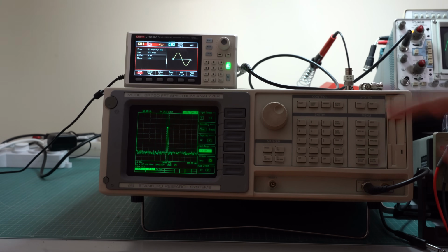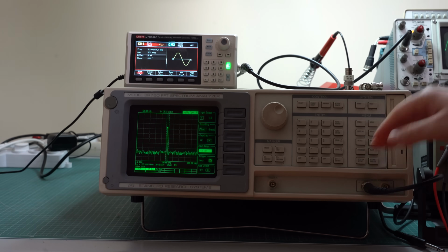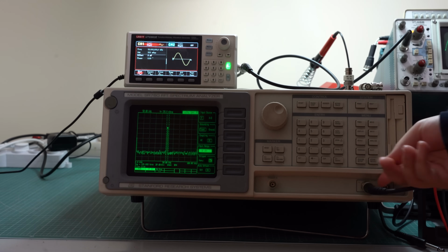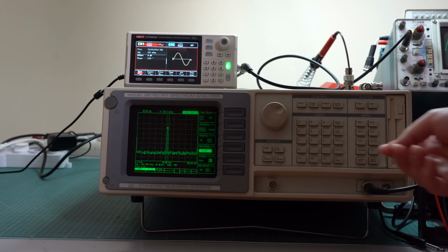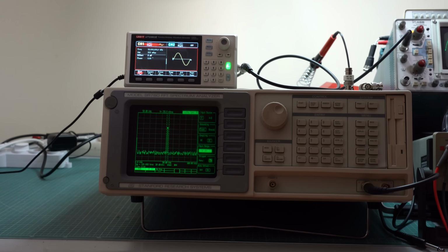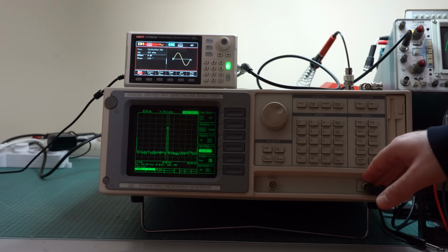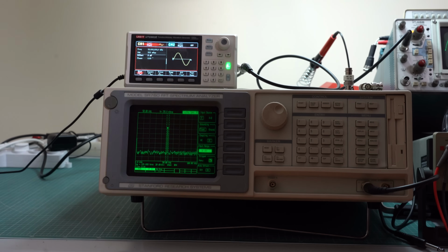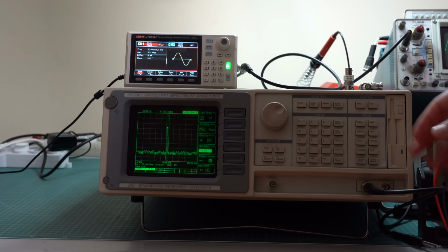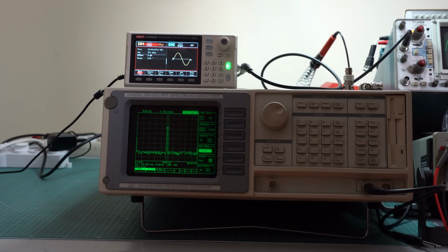No matter what spectrum analyzer you have, it always has a limit for the maximum input level that you can apply to it. So make sure to read the manual and never ever exceed that limit. When working with a radio frequency spectrum analyzer, that level is usually a power expressed in decibels, or otherwise for low frequency stuff it could be a simple voltage in volts, like a peak voltage or something like that.